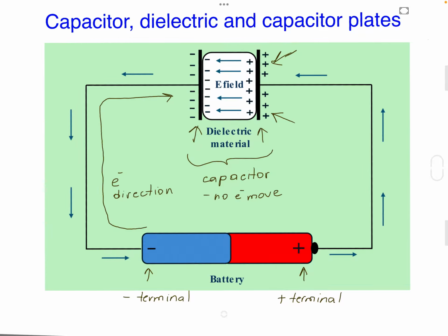The dielectric itself does not have free electrons to conduct current. However, its molecules are polarizable. So what does polarizable mean? The applied electric field slightly shifts the positive and negative parts of each molecule in opposite directions. That's why you see here the positive charges piled up here and the negative charges piled up on the right side of the plate, and this is called polarization. That internal rearrangement reduces the overall, or net, field within the dielectric, and that allows the capacitor to store more and more charge at the same voltage.